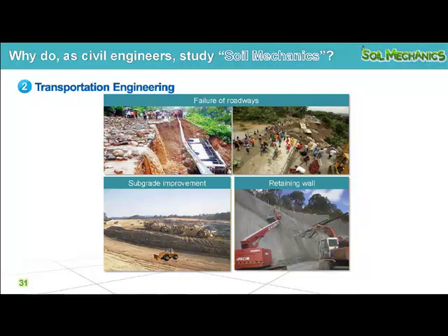So to protect against this really happening, we need to construct drainage or something to remove water, not allowing it to flow across the roadway like this. That can cause erosion and sometimes can slide like here.